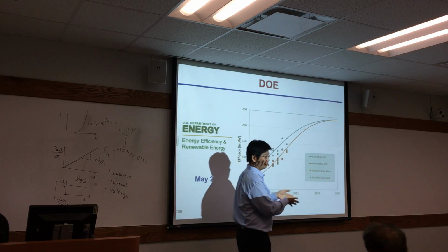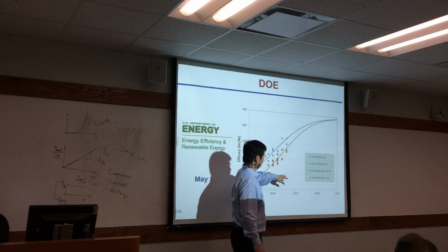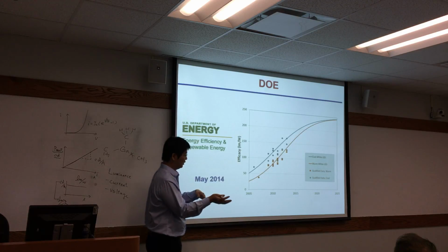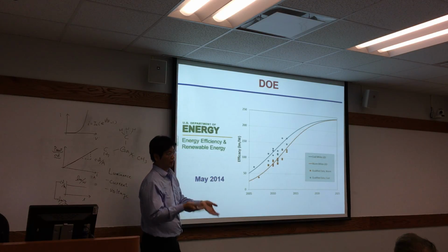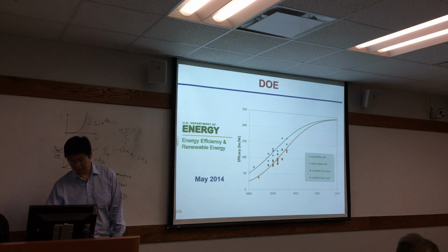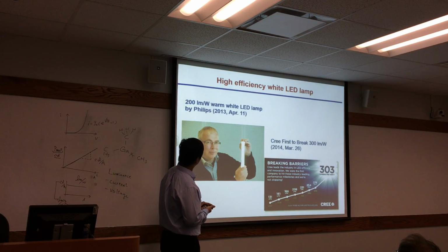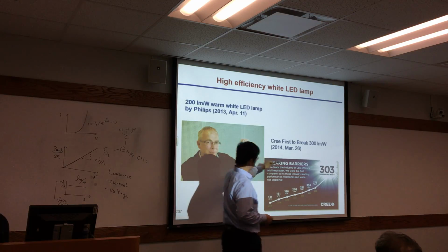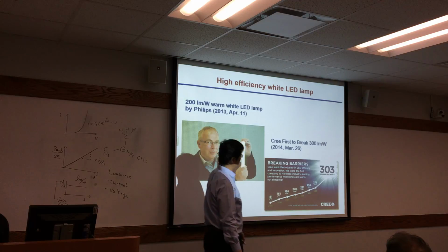Cool white means the stronger blue emission, but that's not easy to obtain the white because it means more transformation from blue to white. And remember that there's an intrinsic Stokes shift, so there's intrinsic energy loss in this. So typically that's lower. So 200 is pretty good. And of course, right now for the white itself, it's over 300 lumen per watt.